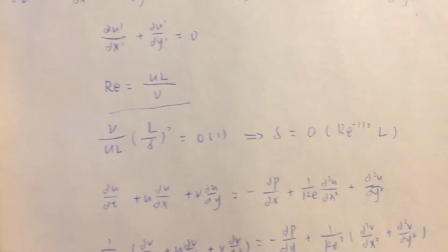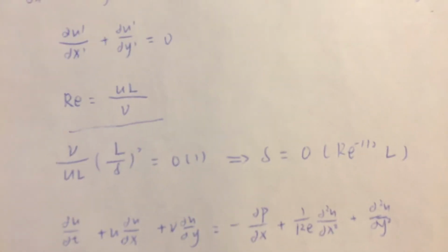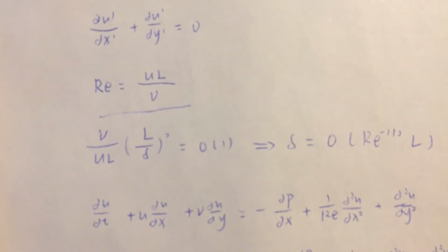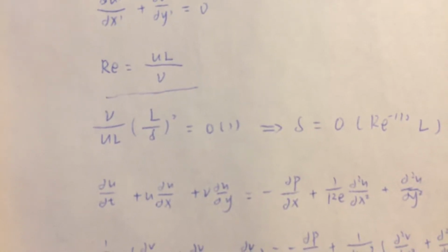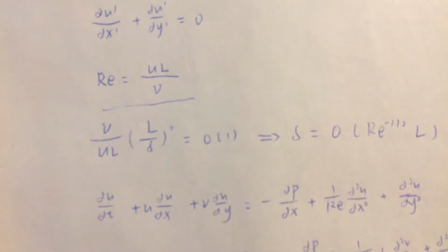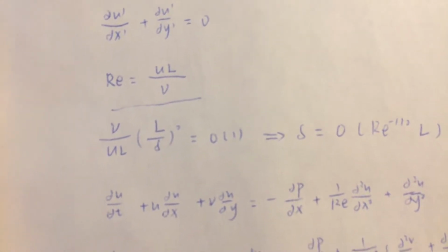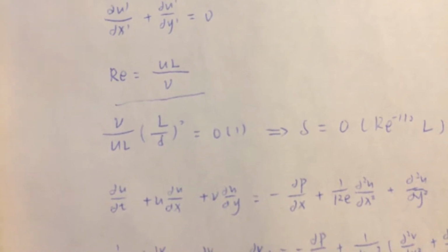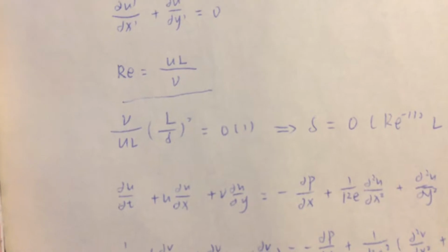Next, if the viscosity is small without being negligible, the modifying effect appears to be confined to narrow regions adjacent to the solid surface, which is called the boundary layer, right? Within such layers, the fluid velocity changes rapidly from 0 to its mainstream value, and this may imply a steep gradient of shearing stress.